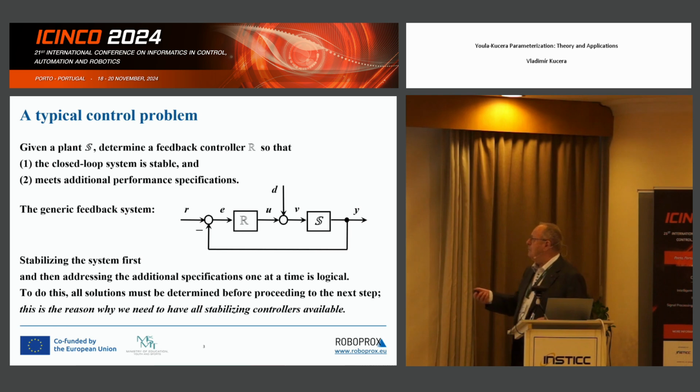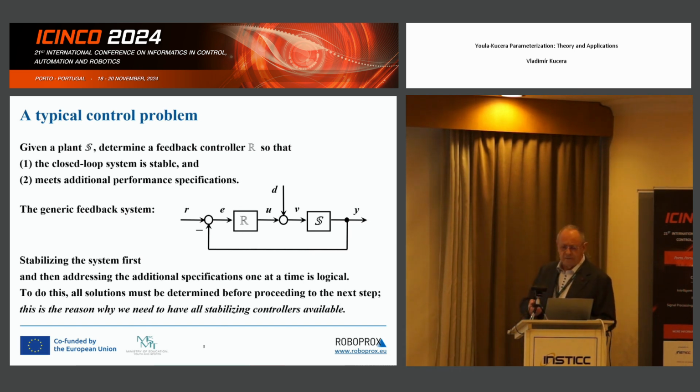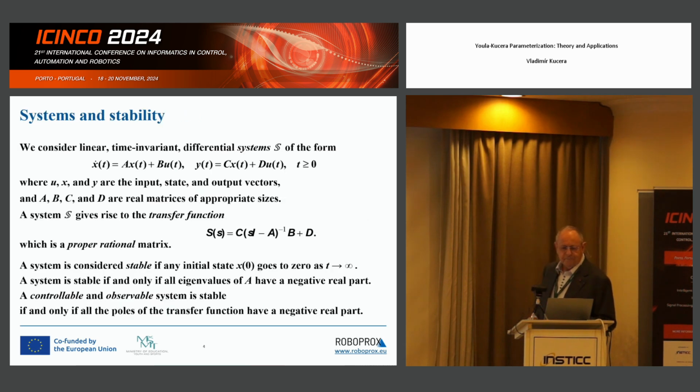And it's quite logical to stabilize the system first because it's the basic specification, stability, and then addressing the additional specifications one at a time. But to do this, however, all solutions must be determined before proceeding to the next step, because otherwise, if one controller is missing, it might be the optimal one. So this is the motivation and the reason why we need to have all stabilizing controllers.